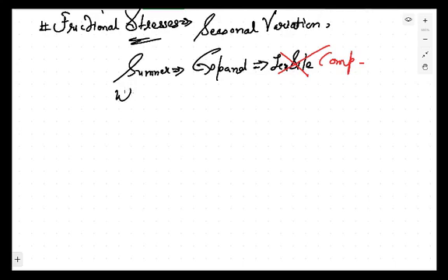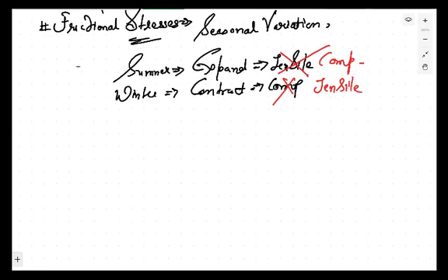Now, in the winter season, the slab will try to contract. But again the same thing. Due to the contraction, the slab wants compressive stresses, but they will not be developed there. What will develop? Tensile stresses. Now, if you see these two cases, in winter there will be the development of tensile stresses, and in summer season, there will be the development of compressive stresses.